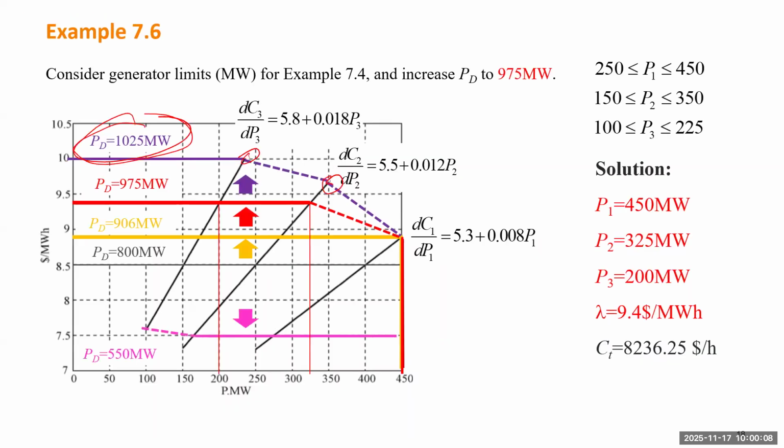Another scenario is if I move down to reach this load and this unit reaches a lower limit, you need to stop here and dispatch for the other 2. So you will have a piecewise linear curve moving up and down to intersect with all the incremental cost curves, and together the intersection points will give you the total load. Then you'll find the solution. All right, good.